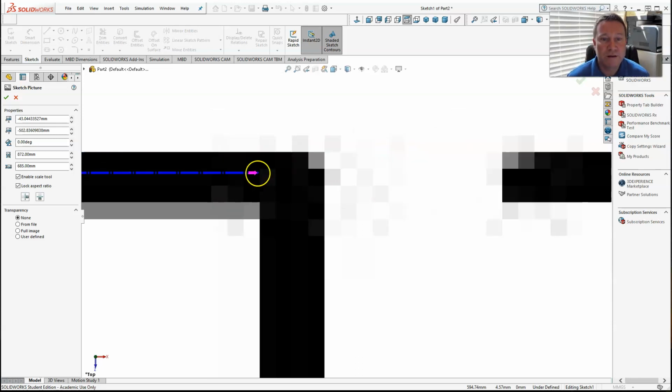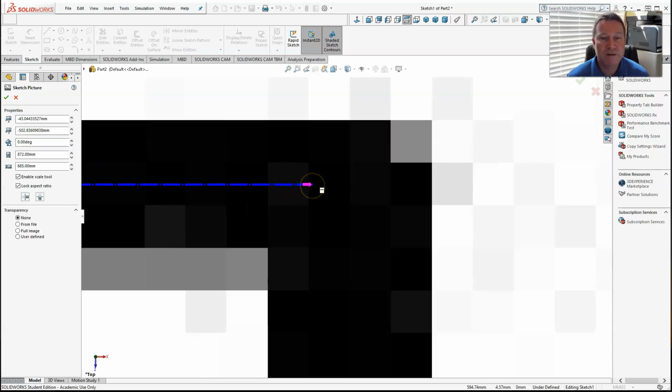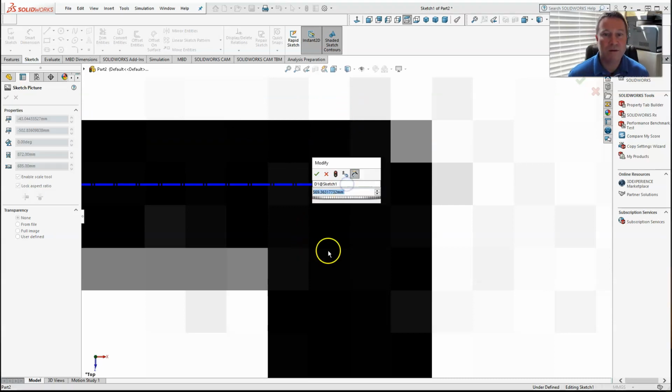Now, similarly, we already pretty much fixed the horizontal. Let's go for the vertical. I'm looking 1, 2, 3, 4. It's pretty solid. So right along this line should be the center, and there we go. Guessing. Oh, see, one thing I forgot to do, this is one good thing that we talked about in the previous example, is make sure you always change your units to what your drawing is. And our drawing is imperial, so it's in inches. I left it in millimeters, but no problem. I can fix that after this function.